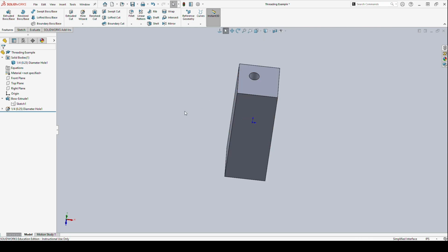Now the other thing we're noticing with this, if I drop this down, I have 2 sketches. This bottom sketch right here, which is highlighted, but you can't see it as well as we could a little bit earlier in the video when I circled it before, is the sketch used to revolve and cut this hole. And then this sketch right here is our second sketch, and this is our underdefined sketch, which shows us we have some problem going on here.